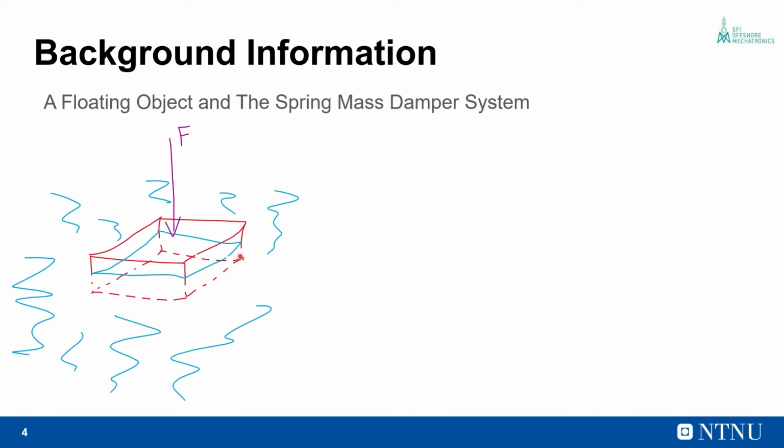And as it moves down, the submerged volume increases, the buoyancy increases, and there will reach a point where the buoyancy exactly matches the total downward forces. But the motion of the barge does not stop at that point, because as the barge starts moving down, there is a velocity and an acceleration associated with the motion, and hence there is inertia in the downward direction. And so the barge will move past the equilibrium point and come to rest as buoyancy overcomes this inertia.